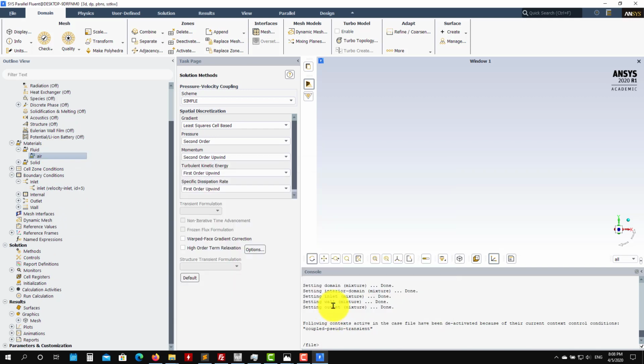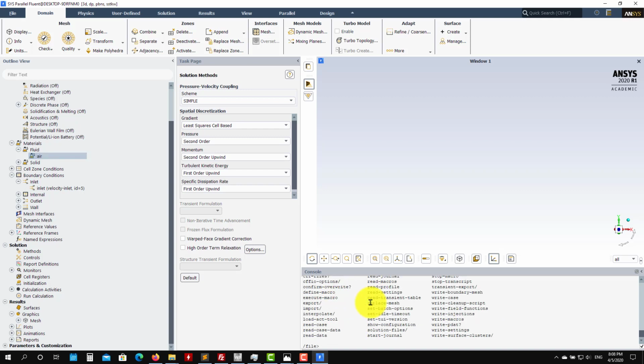Sometimes you have very large meshes that will take a lot of time to open, and then setting up everything can be slow. You get a small mesh, set up everything there, name of the patches, everything, save this setting file, and then apply that there using the text user interface. As you can guess here also, you type Q and just go back one level.